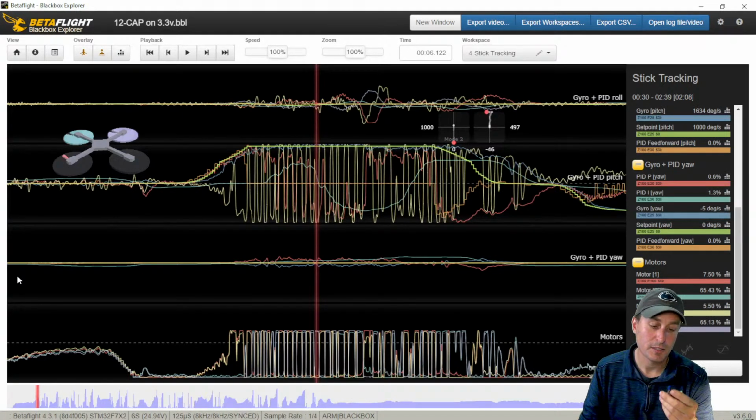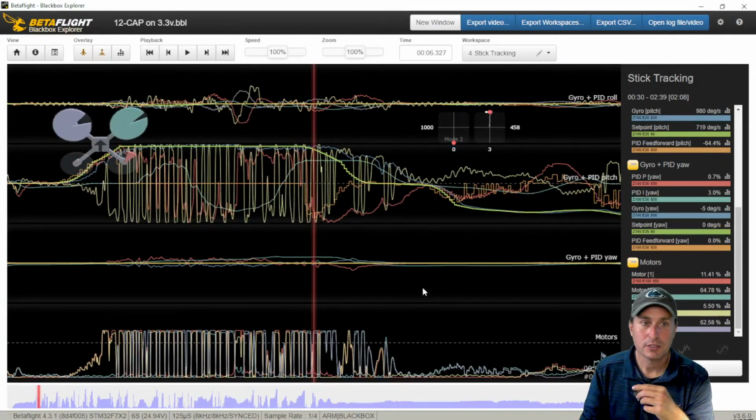And then if you get some lower voltage capacitors, I'm going to do some future videos on that and see if that works out. But I know putting a capacitor on the VBAT of the flight controller directly does definitely help. So that's what pitch looks like.